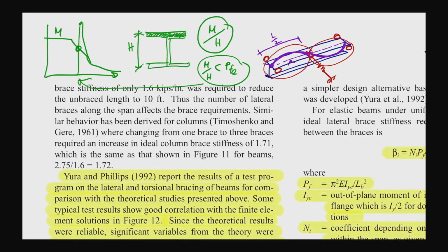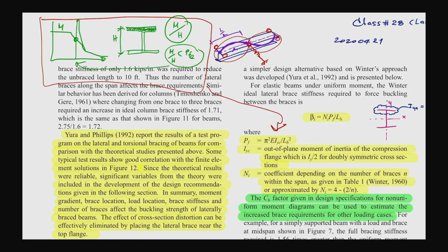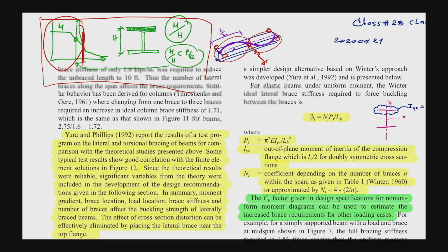So we are coming down to the root derivations of this formula for the brace stiffness calculation. Anyhow, we are going to have a lot more after this one, but at this point I think you understand how the estimation comes about, and when you should use the Pf computed from the elastic buckling theory, and when you should estimate the flange compression force from the moment, because your moment is not going along with the Pf under inelastic buckling. Anyhow, you should be on the conservative side, but when you are too conservative, you do not have a job. That's the thing.